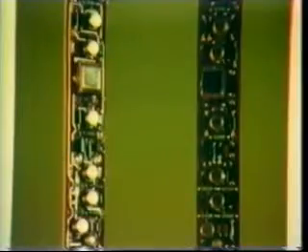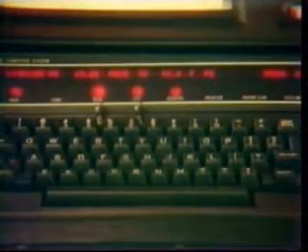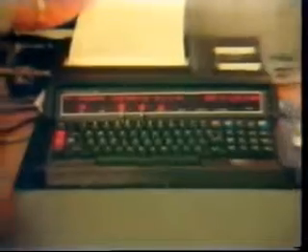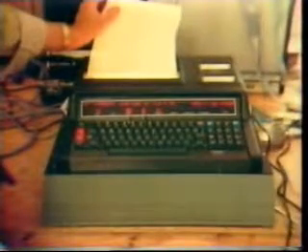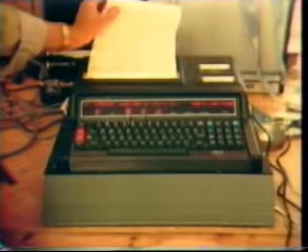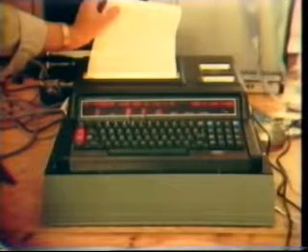Electronic gauges using quartz crystal or strain gauge transducers provide high-resolution pressure and temperature measurements. The electronic gauges may be coupled with downhole electronic memories or connected through an electric wire line to surface instruments. The downhole memory recorder can be set to record pressure and temperature on a periodic basis at intervals from 5 seconds to 128 minutes. Upon retrieval, the information stored in the memory is read by surface electronics to provide an immediate digital printout of the data.